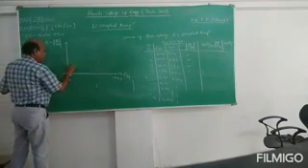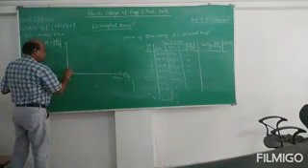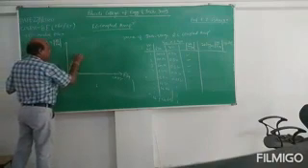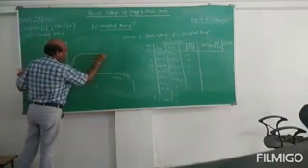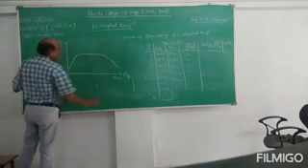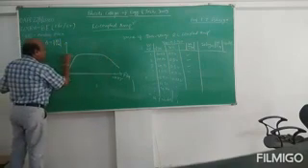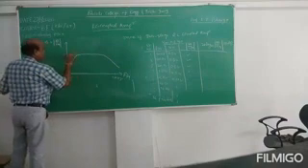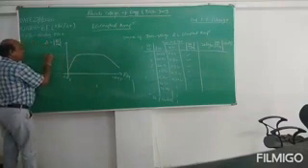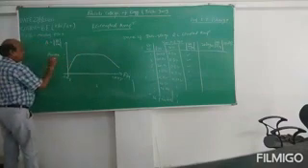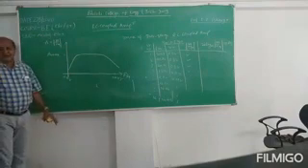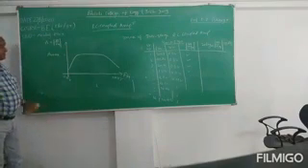Make a certain scale on this frequency and mark the maximum value. So this graph will be something like this. You will plot this graph and get a graph like this. So this maximum value you will get here. This is called the mid-band gain. This is called A max, the maximum gain you will get here.